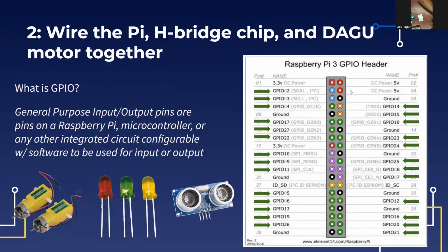If you look at this schematic, or pin out, right here, you can see what each pin does. Not all of them are the same. Some of them have different functions because they're connected to different circuitry within the microcontroller, or the Raspberry Pi or whatever computer it is. So you have 5 volts. This is your power, or VCC as it's most commonly referred to. Then you have your ground. Connecting 5 volts to ground will create that potential difference. Don't do that, but that'll be useful for later.